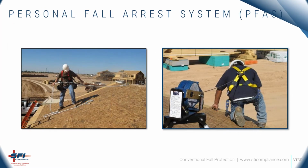The final type of conventional fall protection system we will cover is the personal fall arrest system, or PFAS. A PFAS consists of an anchorage point, a lanyard or lifeline, and a full body harness. These systems don't prevent the worker from falling, they just arrest the worker after they have fallen. With a PFAS, the system must prevent the worker from free falling more than 6 feet or contacting the level below. When using a PFAS, a rescue plan must also be in place to get the worker after the fall.